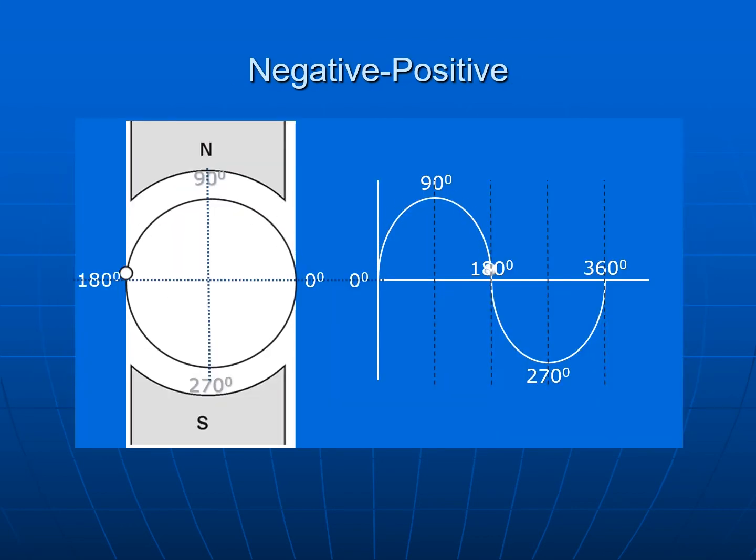Now consider how a conductor rotates through magnetic lines of flux inside a generator. It's always changing direction. As it goes up and around the circle, it's always going to be producing different amounts of voltage as well. Anytime that I pass by the 0 degrees on my sine wave, for example, it's also the same point that my conductor is running parallel to the lines of force. There's no generation, therefore it's at the 0 point inside my sine wave, and that happens twice. It happens on one side and then on the other side, at 0 degrees and 180 degrees.